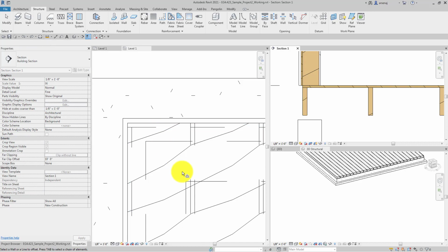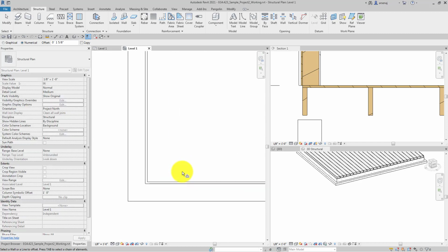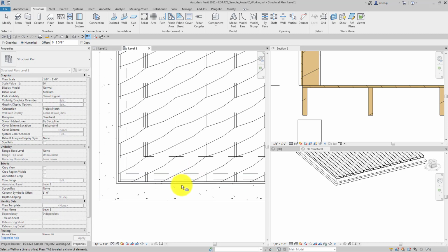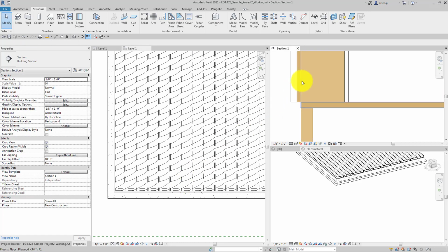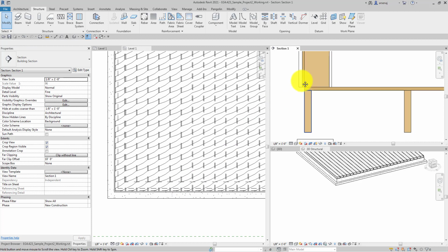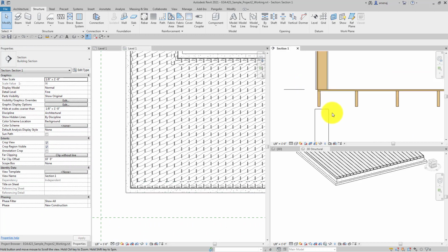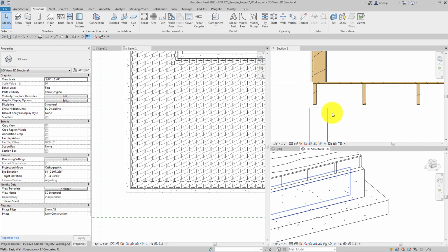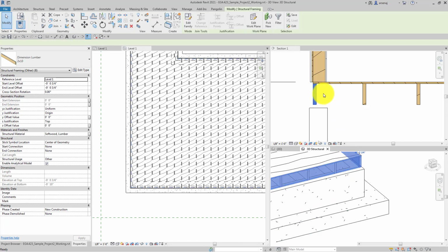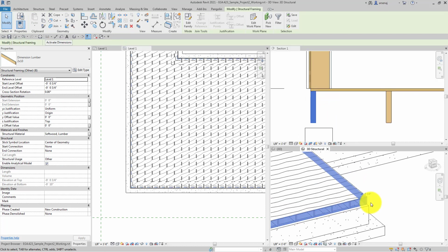hopefully, as we can see, it placed all of the beams, or all of the joists, because this would be like the header joist that's going to be around the perimeter, at this outside, exactly lined up with the face of the stud, plywood, and now this joist is all aligned. We then can also place, and then that was global because we selected the beam around here, so it did it in all the locations.